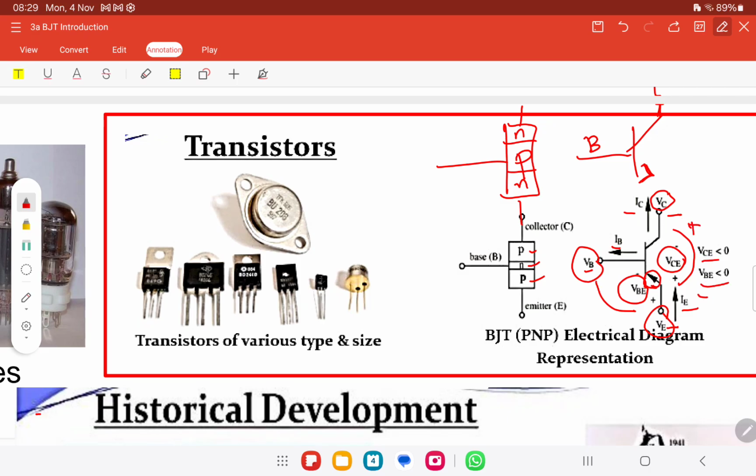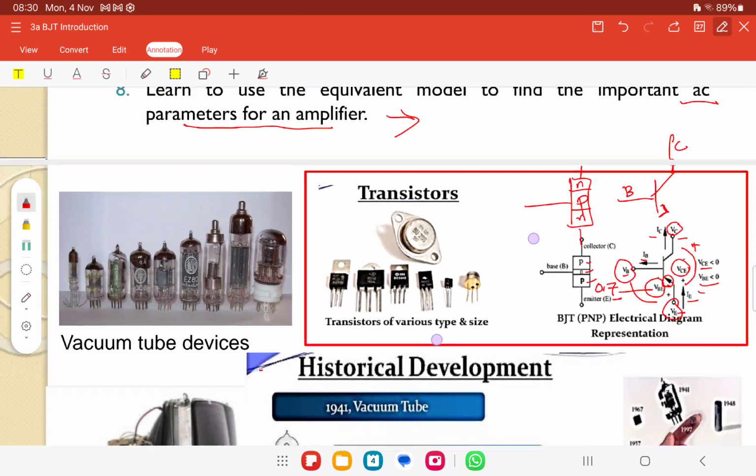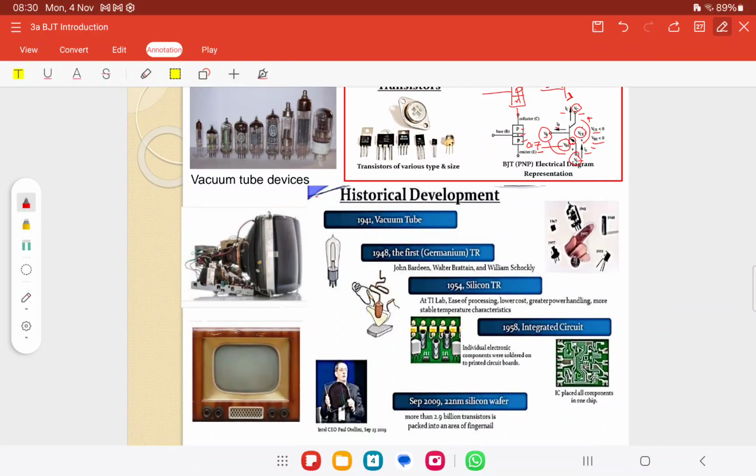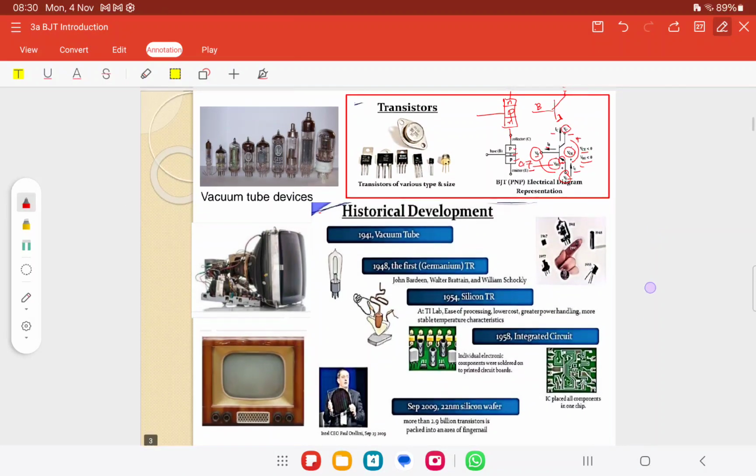Okay, there is an in-between voltage. And for VBE, this one equals 0.7, the same value as a diode. VBE must be 0.7 all the time. In the calculations, they will not give the value of VBE, because by default VBE is all the time equal to 0.7. Later we will look at it in more detail. That one is in DC analysis. For voltage and current, these are the values we will calculate in DC analysis. Alright, so this is the history of the transistor.